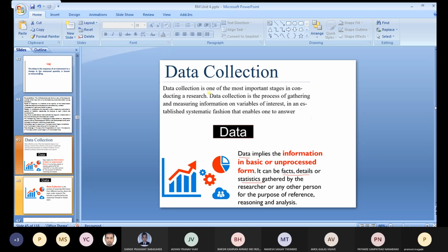So with respect to competitors, we are studying, that is benchmarking. Then we check whether for push-pull it should be a plastic snap or a metallic snap. For the snap, we have to decide the material. Then what is our working condition, which materials can be used in that working condition at that temperature value, and what forces we will require. So we do a comparison of materials. This is the process we are following.